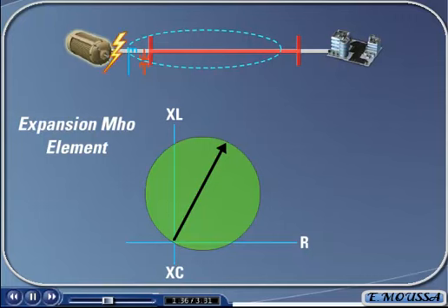On faults that occur very close to the point where the currents and voltages are being measured, some relays may have difficulty distinguishing whether the fault is inside or outside their zone of protection. To overcome this difficulty, the relay can change the size of the Mho circle when the calculated impedance is very near the origin. This is sometimes referred to as an enhanced Mho element.